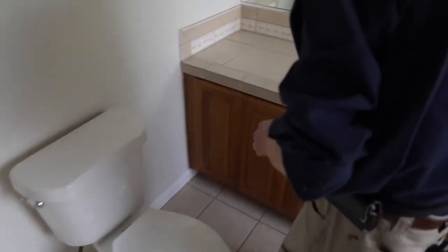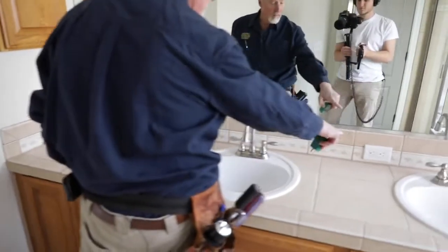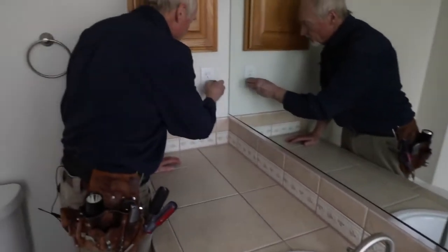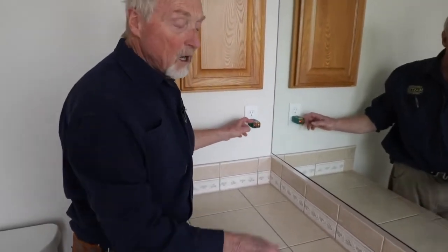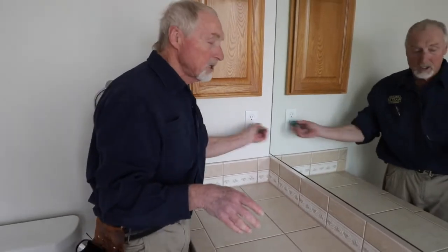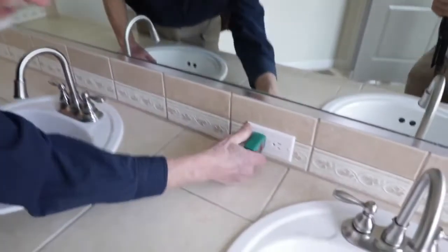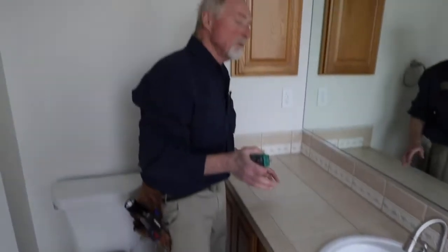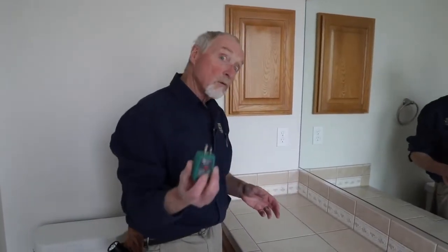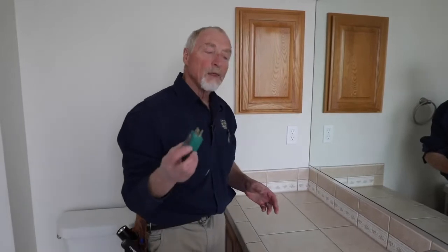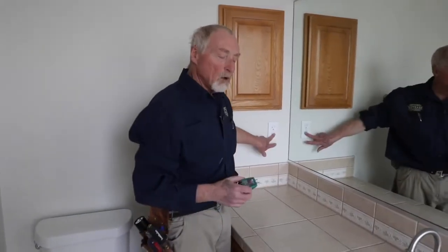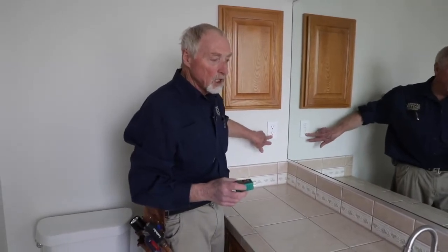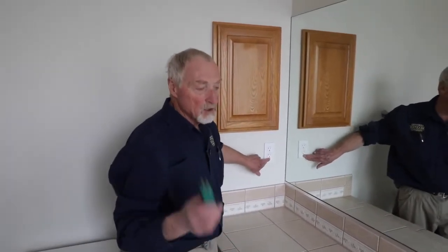Looks good. Take a look at my sink here. We have a GFCI here, which again is part of the electrical, but I'm here, so I'm going to be checking it. This GFCI may be controlling our basement. So it's probably controlling our basement bath also. Since I tripped it remotely from the basement bath, it's tripped here, dead there, showing hot neutral reverse here, which is an indication it's wired incorrectly.